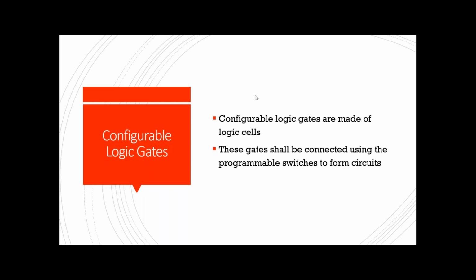It's like a lookup table. How you program that lookup table constitutes the circuitry you want, right? Assume it's a small logical cell. Don't think about the full FPGA IC, which consists of millions of logical cells. Think of a small logic cell. The same logic cell can be programmed into an AND gate, or a NOT gate, or any gate. Maybe we will start with a very simple example.